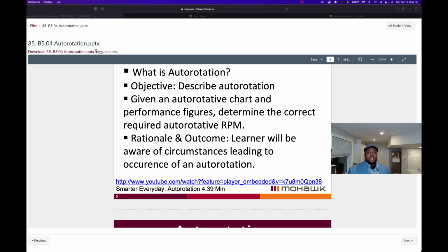Conversely, if the rotor RPM was too low, we would lower the collective to reduce the amount of drag and give the helicopter blades an opportunity to maintain or increase the stabilized rotor RPM as desired. So the collective is adjusted to increase blade angle, which helps us maintain proper RPM during descent.